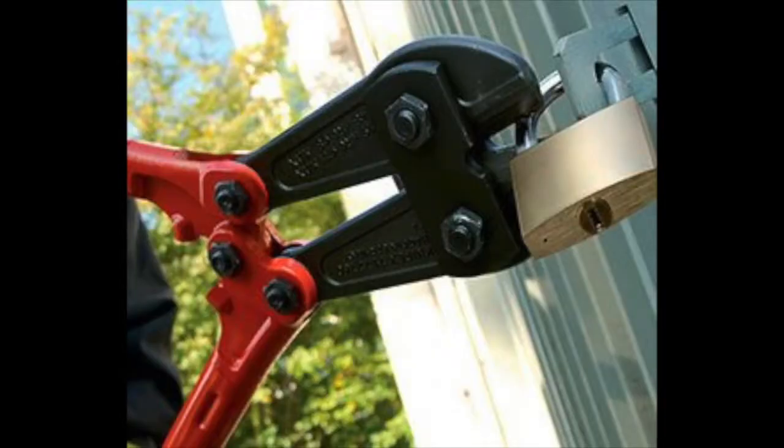For the functional requirements of our shackle, we determined that the lock must withstand the tensile strength of a human pulling or prying at it, meaning it must have a high tensile strength. We chose at least 800 newtons for our minimum, and this was chosen based on the average weight of a person and the force of gravity.